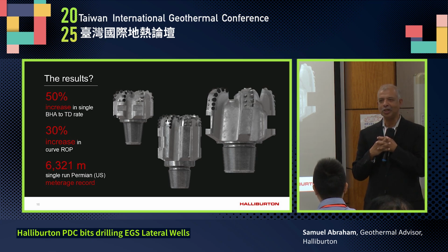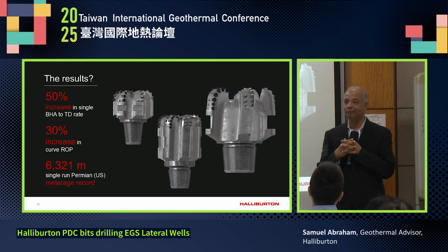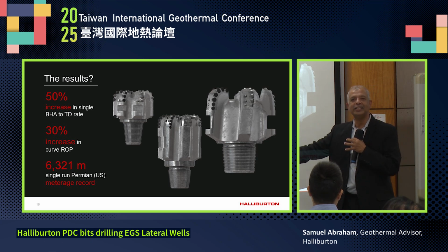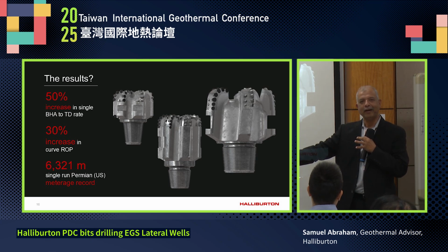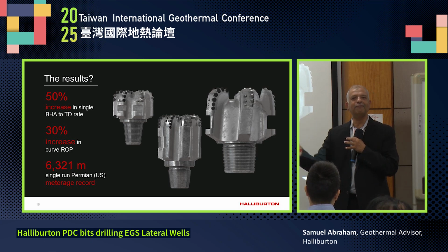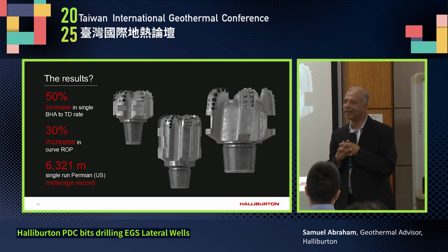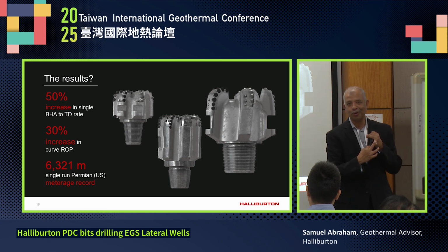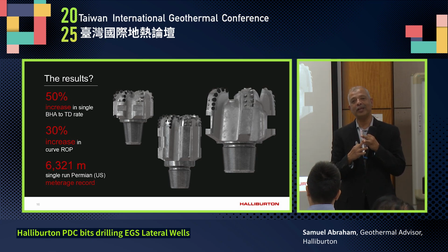This is very important because many times people want to drill faster. They use tricone bits or even PDC bits. Sometimes they want to drill faster, but they are not looking at any gauges in front of the driller. Finally, what happens? Either you come out with 3 cones left in the well, or you come out with a bit that has had some problems. What does that add up to? You have to spend time to fish those PDC cones, tricone bit cones, and clean up your wellbore before you can drill further. Just some practical aspects of why you select a bit.